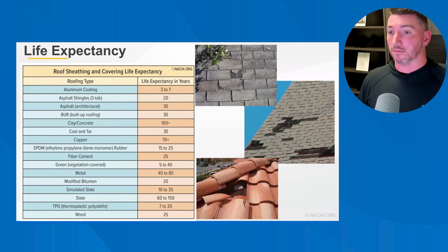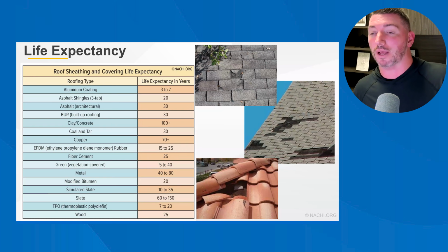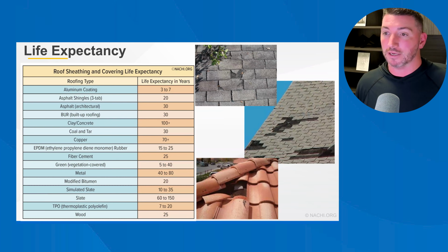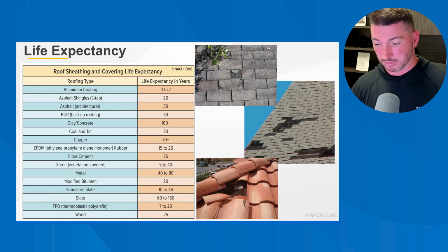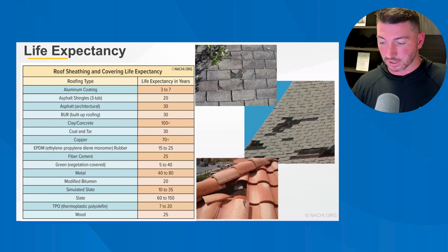And unless you're using 3/4 inch plywood up on a roof, which is not very common, most of those sheathings are not allowed to span more than 24 inches. And in some cases, 24 inches is even too much. And you'll start to see these waves in the roof decking, and it'll just look very unsightly. Installation defects. All roofing systems are only as good as the installer, and it's not uncommon to see all types of failure due to poor fastenings or other installation problems.